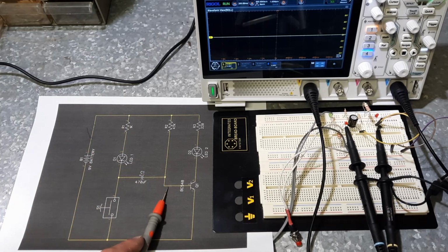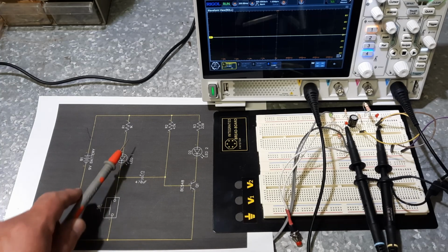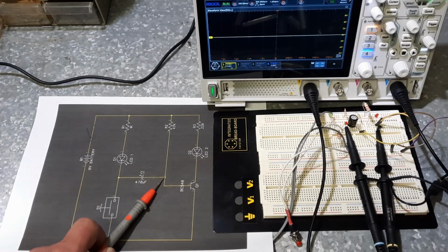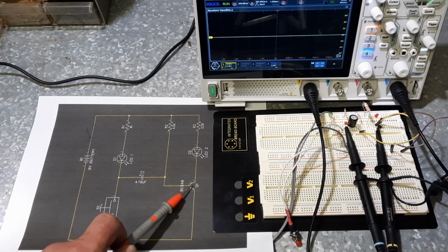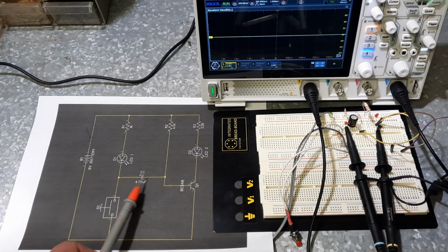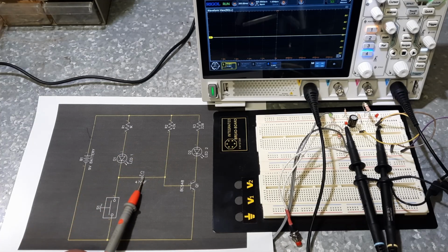So what we're going to see is it's going to start from a negative, and it's going to slowly rise to a positive. Well, it's going to go through 0 first, because this is trying to equalize this cap. And as soon as it gets to 0, it's then going to try and rise up. What we're going to actually see on our scope is, with me holding this button, once this capacitor has equalized, so it started out charged, we push this button, it's now being forced to discharge.